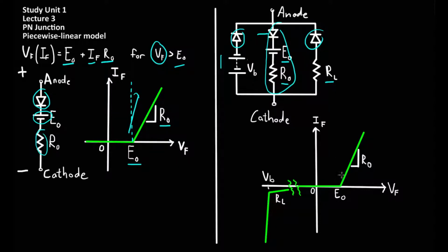In much the same way as the forward voltage would exceed the turn-on voltage of the diode, it would conduct current in the forward bias region. When the diode starts to enter breakdown, once the breakdown voltage is overcome, then the ideal diode in this branch will cease to conduct and current will start to flow through this branch here, which models the behavior during breakdown, where the reverse current to the diode actually starts to flow at the breakdown voltage.